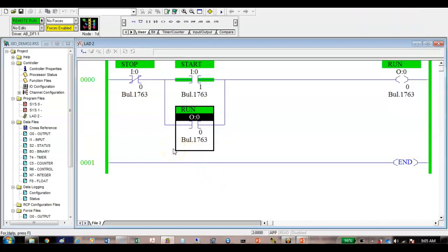So when I press this button right here, now we got a problem with this because I'm using a normally closed push button. Somebody would have to sit here all day long and hold this button, which is wrong, right? Unless I come over here and use the normally open to input 0. So I'm going to go over here to the other one. I think I've already got it jumped out. And we'll move this over to here. So this is the normally open push button. So now it goes true.